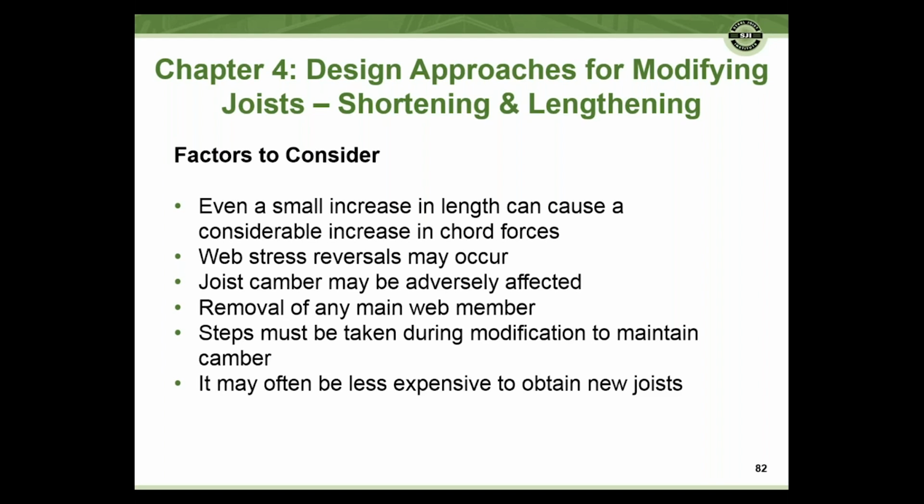Although you may only be saying, I just need to add a foot, you can cause a lot of increase in member forces, especially in your chords, and you may find yourself having to reinforce top and/or bottom chords where you may not think you need it. Be careful, because interior webs can go through reversal. As you start increasing a length, all of a sudden a tension web can turn into a compression web. Be very careful of that web stress reversal.